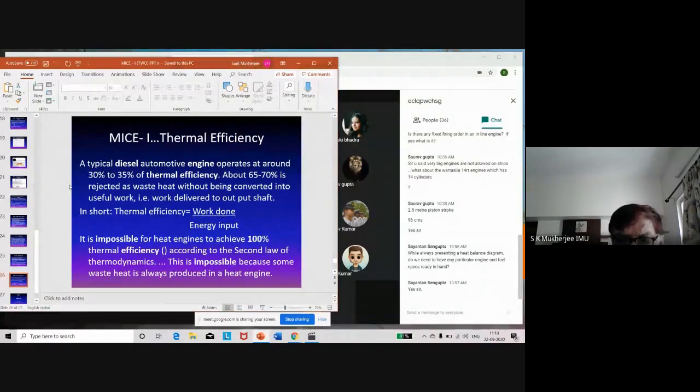Number three, the cooling water, which is used for cooling your engine, can be utilized in a freshwater generator. In that freshwater generator, seawater is passed in, and this hot water is circulated through pipes in the seawater. So the seawater is heated, and the chamber inside the freshwater generator is in a state of vacuum. This vacuum is provided by means of an eductor.